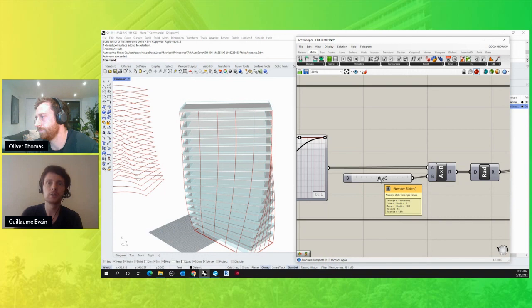What's great on the analysis side is that Ladybug and others existed as software where you needed to import your geometry, run the analysis, etc. And a lot of them, even the structural analysis software, created their bridge within Grasshopper, so you don't really have to access the other software anymore. It's kind of like calling all the functions of the software in the background, and you stay within Rhino, and you can still manipulate everything and get live feedback.